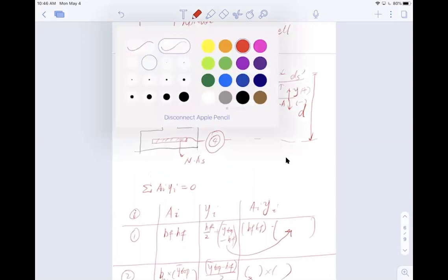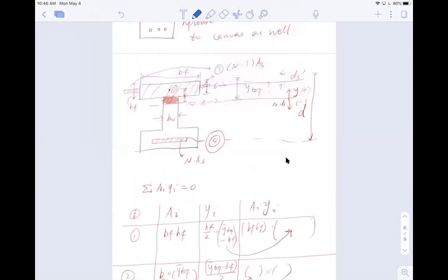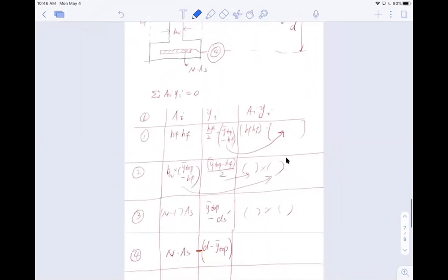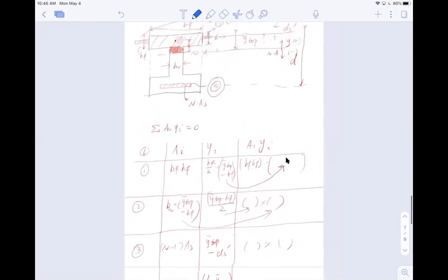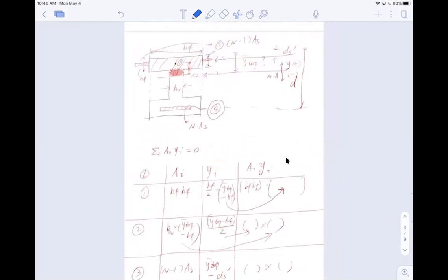The idea of using that equation is an approximation, because if you use that equation, you're basically assuming everything is going to be in the flange zone and the compression is in the flange, and you can treat it as a rectangular section. Right, but it turns out it's not the case. Then you have to do the full-blown analysis. Okay, yeah. That helps. I just wasn't sure. I wanted to do it that way.